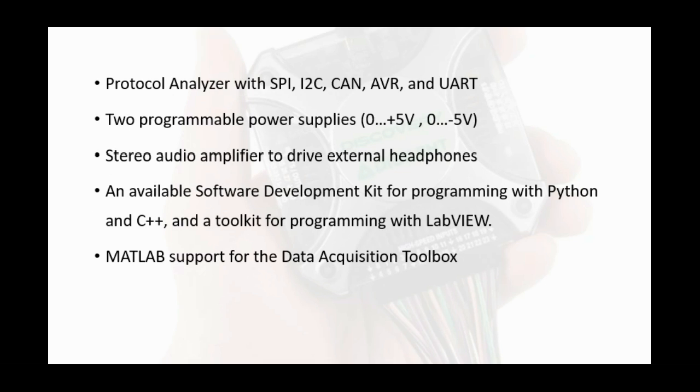And one of the important specifications of the Analog Discovery device is the protocol analyzer. With the protocol analyzer, we can analyze the SPI, I2C, CAN, AVR, and UART protocols that are very useful in embedded programming. Also, it includes 2 programmable power supplies.